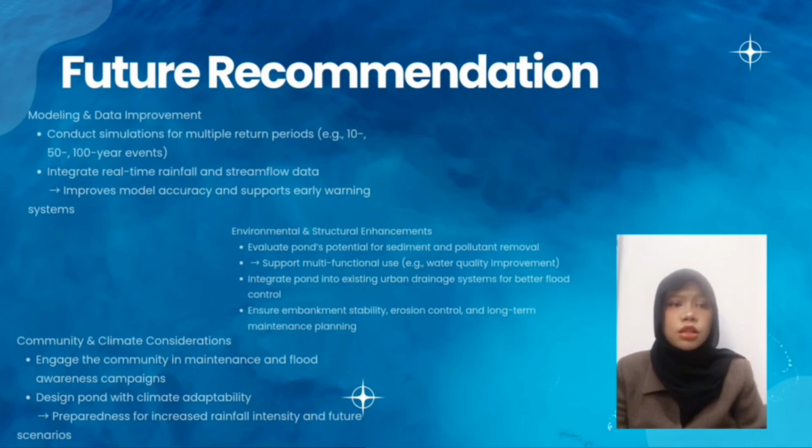For environmental and structural adjustment, evaluate the pond's potential for sediment and pollutant removal to support multifunctional use. Integrate the pond into the existing urban drainage system for better flood control. Ensure embankment stability, erosion control, and long-term maintenance planning.